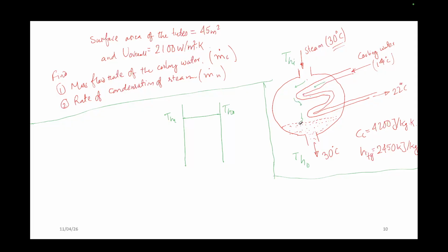You are right. Why? The direction of flow: only in parallel flow will you directly see that these are flowing in the same line. If it is not in the same line, irrespective of the situation, you can consider it as a counter flow. And in a steam problem, in any condition where such lines are coming, you can consider it as a counter flow. Okay.